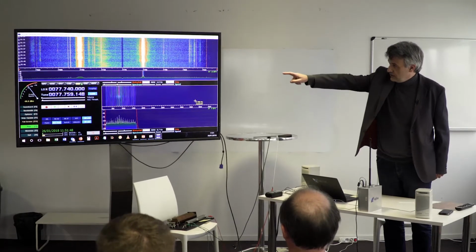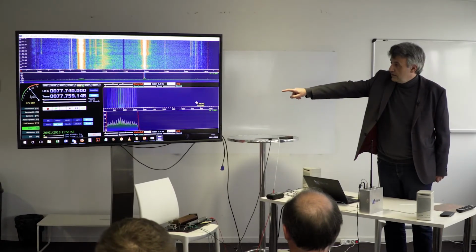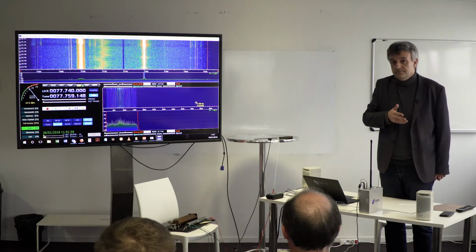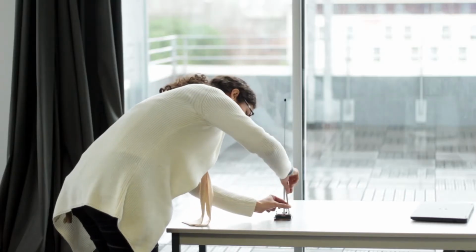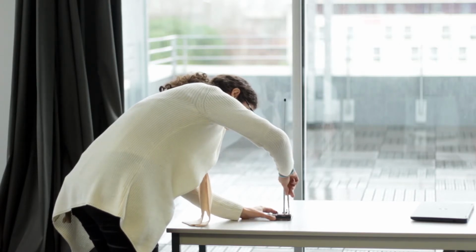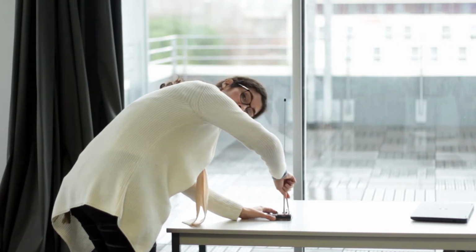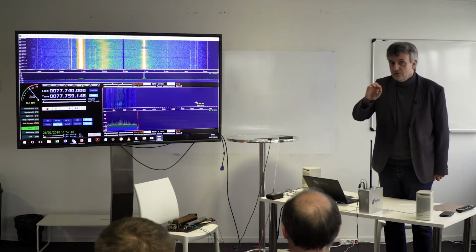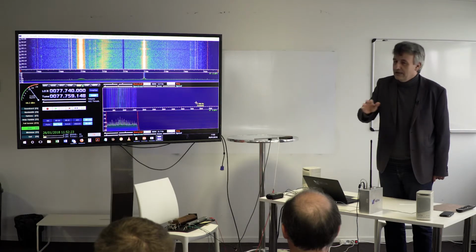So you turn it. You can see the signal here or here. You see that the signal is evolving, increasing, decreasing, etc. So she's really tuning the antenna. Try to tune to the maximum. Yes, here you are. But a little bit before. Go back. Stop. There is a certain delay, so you have to be very, very slow. Well, let's say it's not bad.